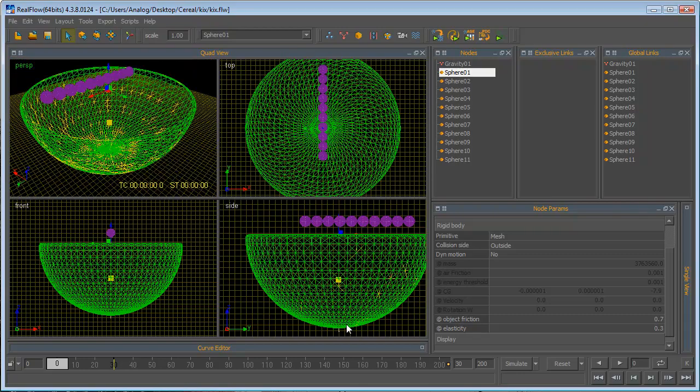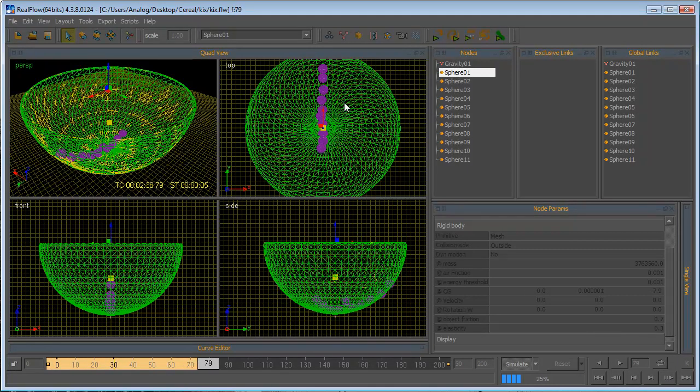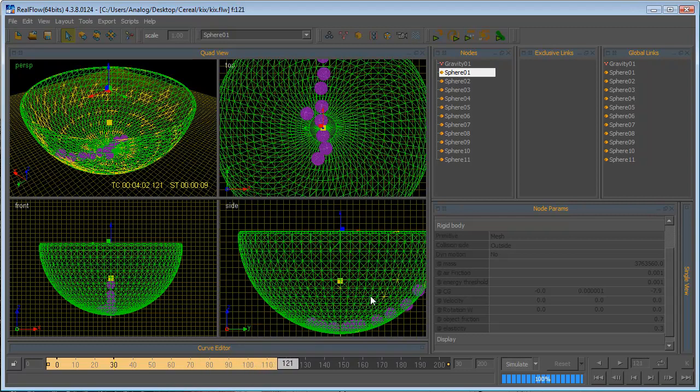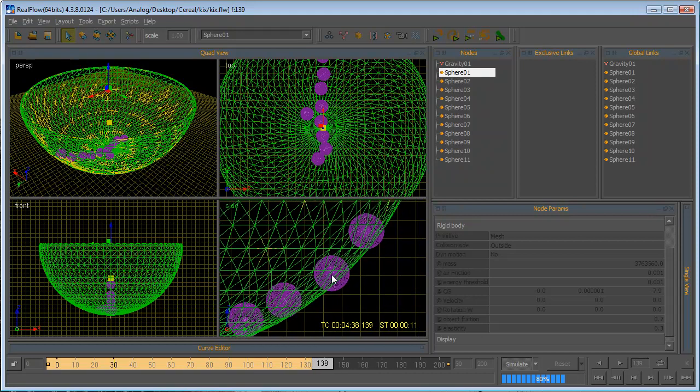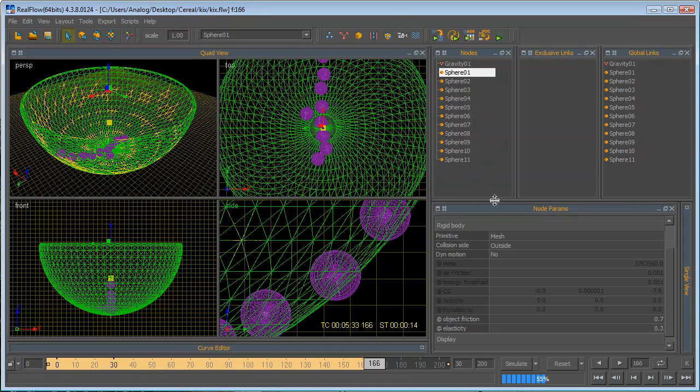All right, let's go ahead and simulate. And hopefully these roll around. Yeah, I see there's kind of some movement there. That's good. Actually, there's one. You see how they're kind of poking through the side here? You see these balls are poking through and they're not really moving that much. We have to go ahead and change this primitive right here, our bounding box, fancy word.